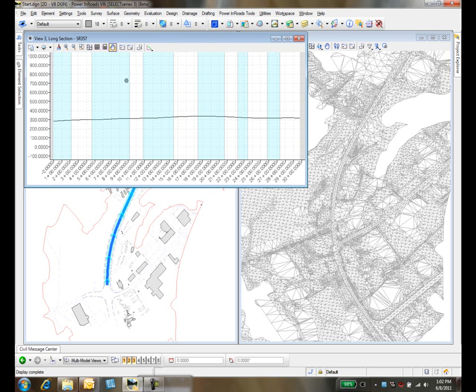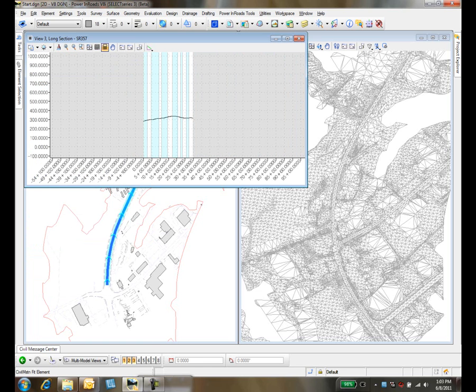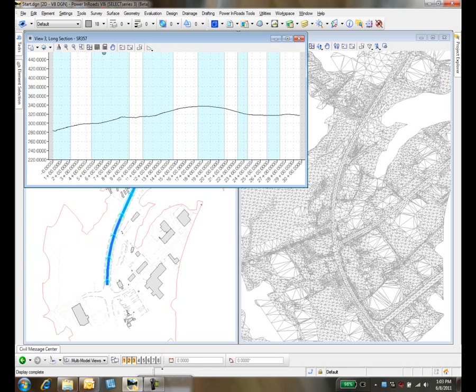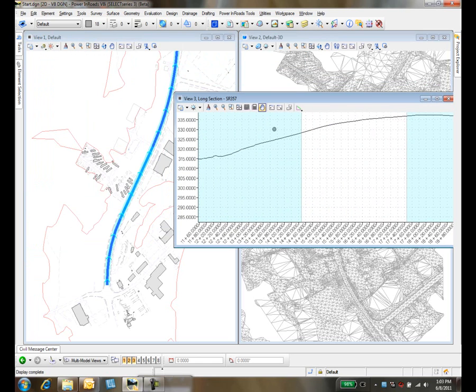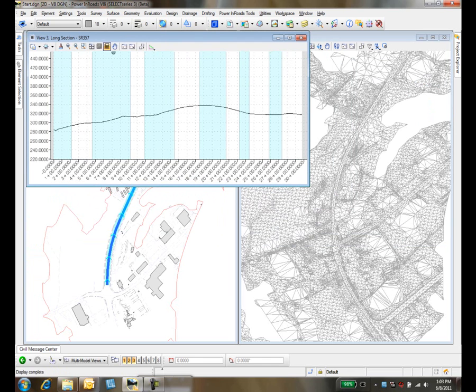Now, this is a new type of view inside of MicroStation. It's called a profile space or a profile view. For example, you'll see here under View Attributes, you've got your standard attributes, but down here on the bottom you've got a new civil option that gives you the ability to exaggerate that view. So in my case, I'm going to select, let's say for example, 5. You've also got the ability here to fit the extent of the profile, or you can fit according to the plan extents, which will fit the profile to match what you see in plan view.